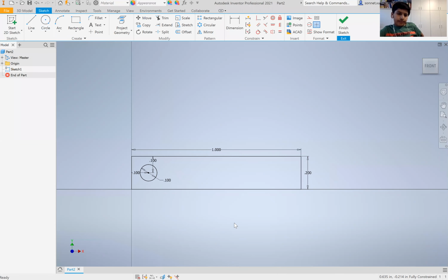So if I want to have sort of like a Lego brick and have like one circle here, one circle here, one circle here, and one circle there, I could make every single circle individually, but especially with really complicated parts, and if you guys remember the robot that I showed you guys yesterday with hundreds of holes, you definitely don't want to be spending hours and hours making every single hole individually. So in this case, what you can do is you can make a pattern.